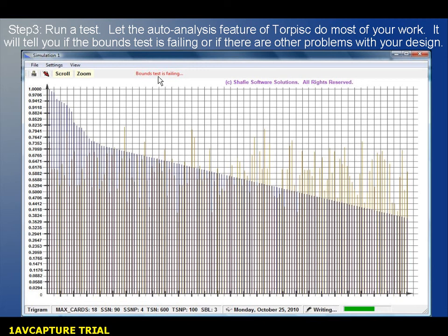To get accurate results, you should let your simulation run in calculation mode for at least 10 minutes before relying on this information. And then if you look at the bottom of the screen, the parameters that you chose before running this simulation are shown to you to make sure that you can keep track of which simulation is which if you're running 8 simulations simultaneously in batches. And on the right side you have the mode, whether it's the write mode or the calculation mode.